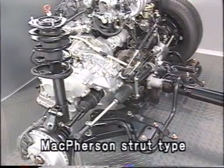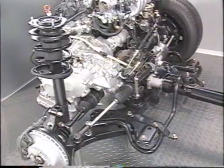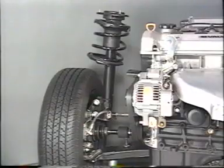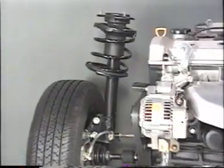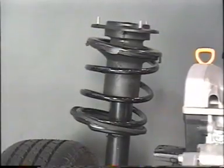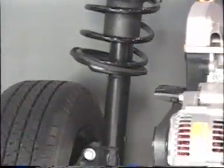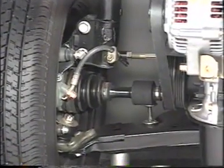This McPherson strut type is widely used for the front suspension of front-engine, front-wheel drive vehicles. This suspension is called the strut type because the shock absorber also functions as the support for the suspension, especially when used for the front wheels. This suspension is called McPherson strut type after its designer.